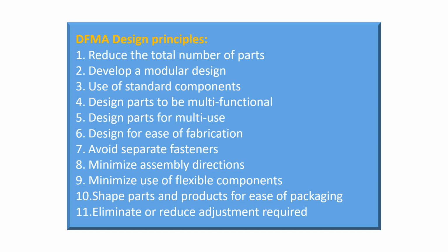Threads, screws, bolts, nuts, should be avoided where possible, especially when using automatic assembly. Instead, quick installation techniques such as various quick-release fasteners and gluing should be used. The number of separate fasteners should be minimized.